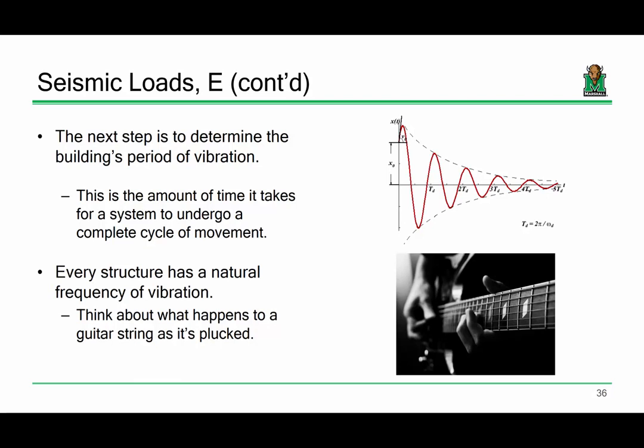Now, what does this have to do with earthquakes? Well, what do you think is happening to the structure during the earthquake? You're taking the structure and it's undergoing a forced vibration. Once that earthquake is over, the building is vibrating under its natural frequency. So the determination of that natural vibration period is incredibly, incredibly important.